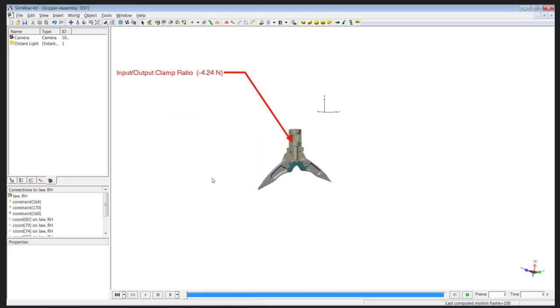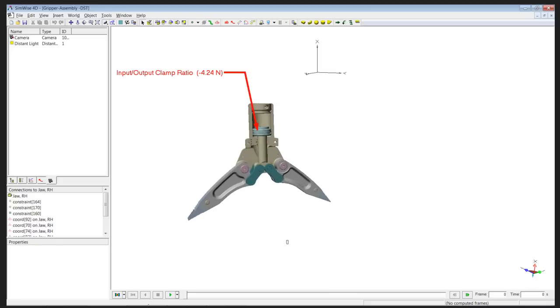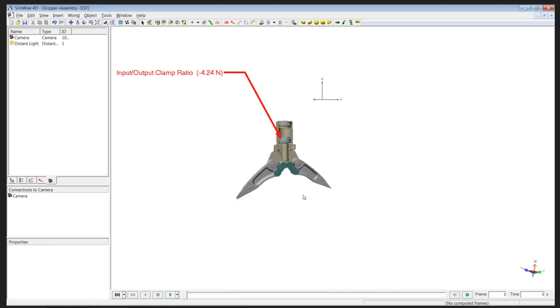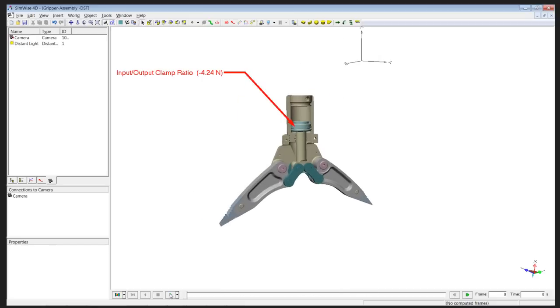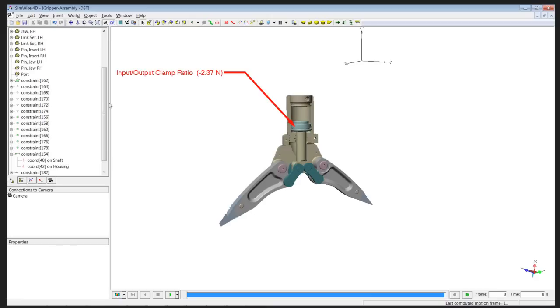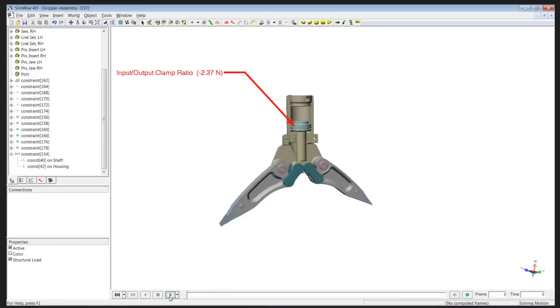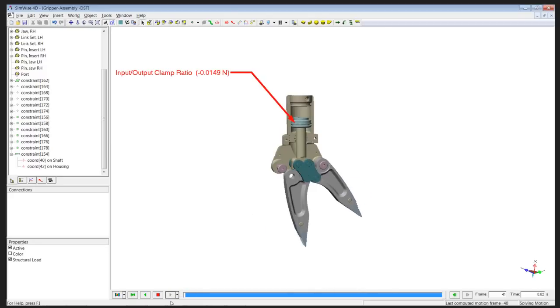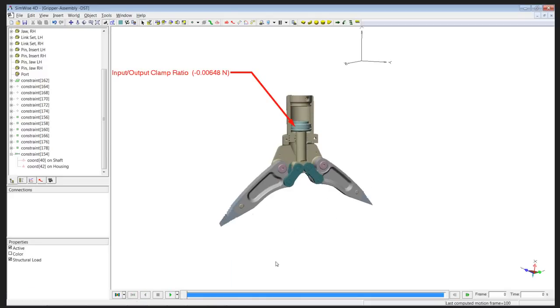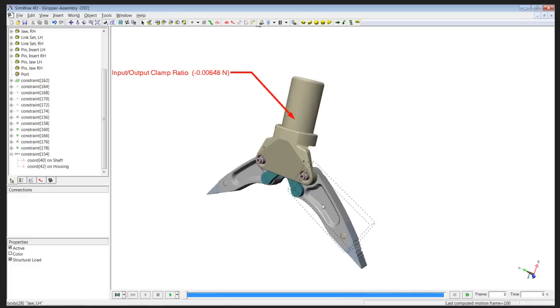I'm going to go ahead and say let's delete it. And I'm going to delete my keyframed animation because it'll be moving around on me if I don't. Okay, so now if I run this, we still have our forces applied on here. Let me delete the forces and I'll run it again. So, for example, we have something that was missing out of the SpaceClaim model, so we can add a constraint in here to correct that.